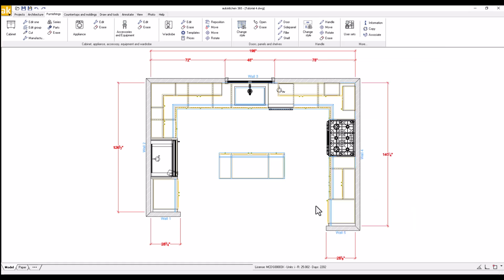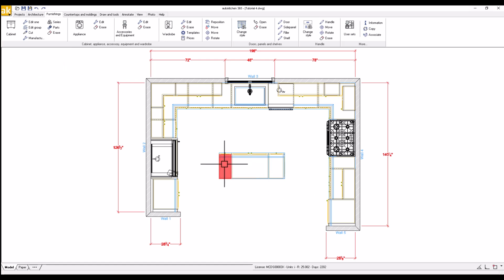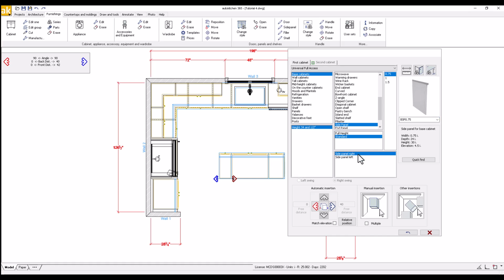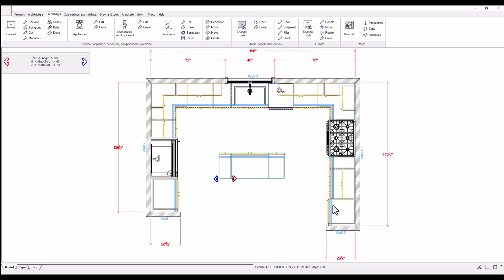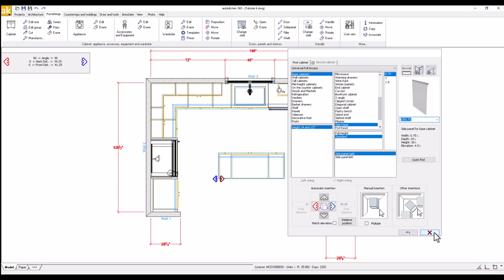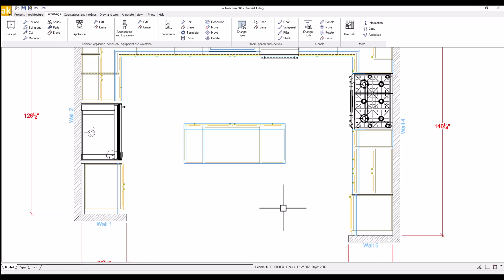inches wide. Next, click on the white cube and click the drawer cabinet 12-inch. Select a standard side panel, right 0.75 inch and click the blue arrow to place it. Close the cabinet insertion window. Next, we are going to place a back panel on the island that will cover the back of the 3 cabinets plus the 2 side panels, one on each side.